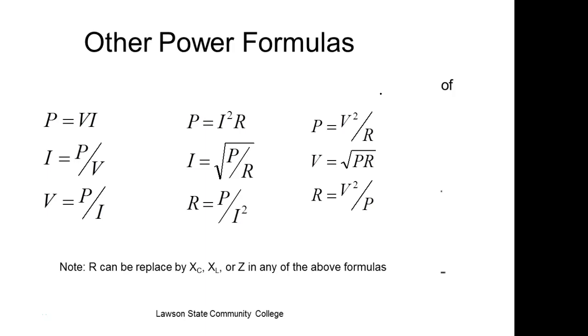Slim to none, because you don't have a regulator, they feed you through transformers. Now, they have taps on their transformers when they hook it up, and they try to get it as close to 240 as they possibly can. But they'll never actually hit it, right? So if this house over here, their voltage is a little less, then odds are they're going to pay a little less power bill. But you can't put it too much, or your motors or stuff won't run, right? So everything's rated over a voltage range.